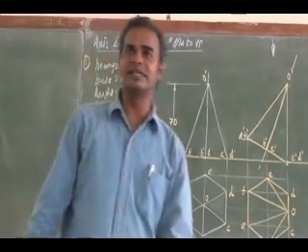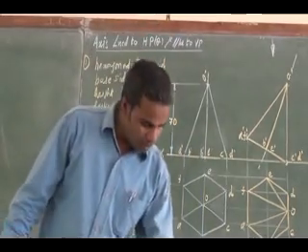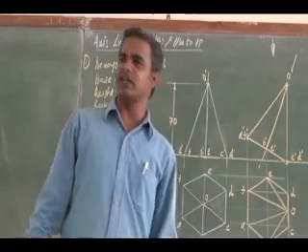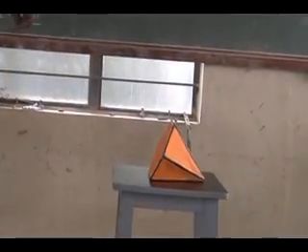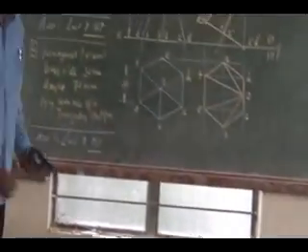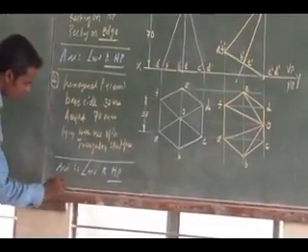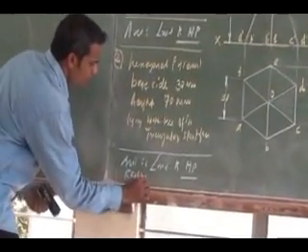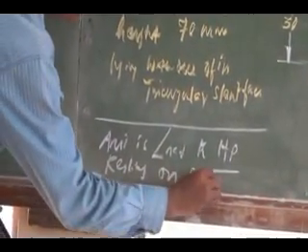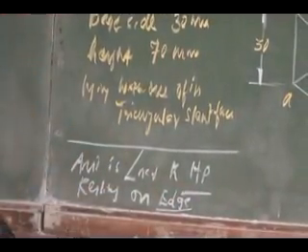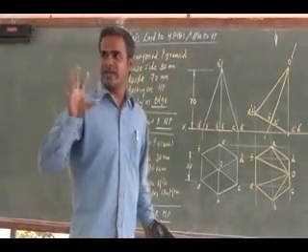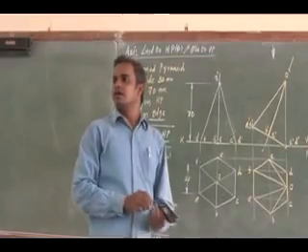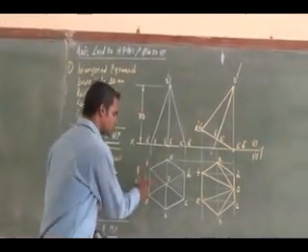Now you see, in this orientation, in the base, which one is touching the ground? The edge. In the base, the edge is touching the ground. Right. So it is a problem related to resting on an edge. So this is also hidden here. So you have to draw the true shape of the pyramid's base such that the edge is at the extreme.